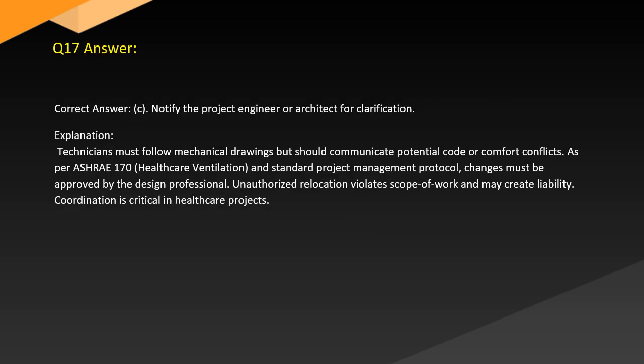Answer. Correct answer: C. Notify the project engineer or architect for clarification. Explanation. Technicians must follow mechanical drawings but should communicate potential code or comfort conflicts, as per ASHRAE 170, healthcare ventilation, and standard project management protocol. Changes must be approved by the design professional. Unauthorized relocation violates scope of work and may create liability. Coordination is critical in healthcare projects.